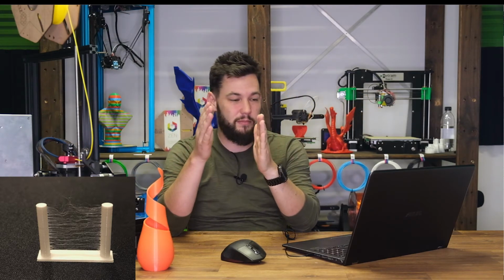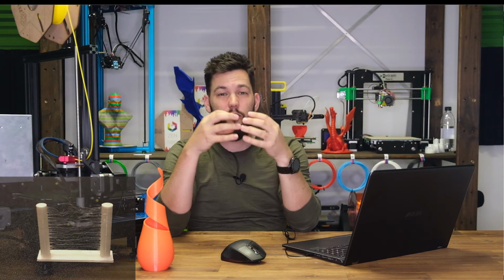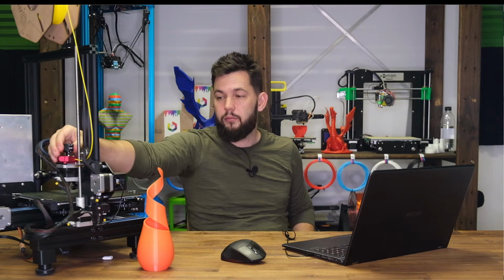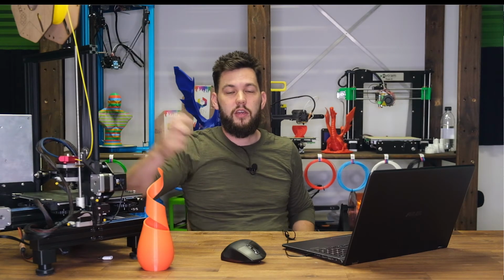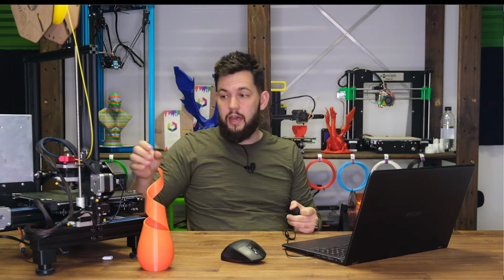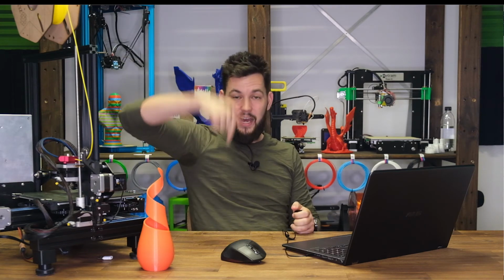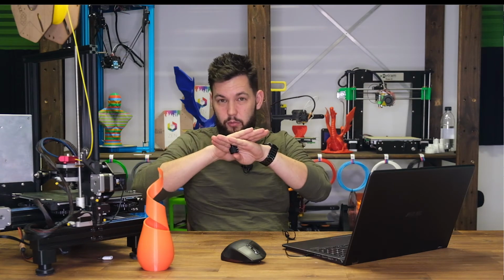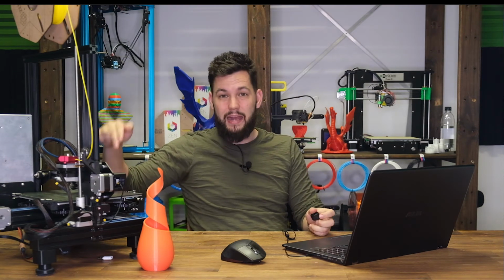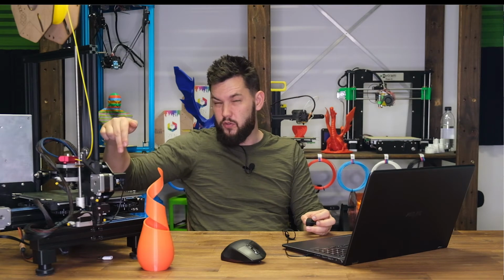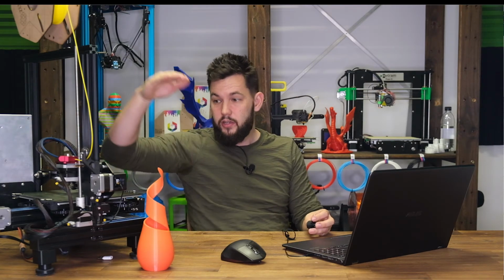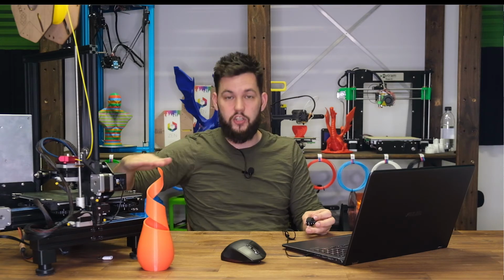So very similar concept. How we get around that is we do something that's known as retraction, and that is where the extruder motor over here, a little print on it, this will move backwards very quickly just before it starts to travel, which will suck the filament back up the nozzle, trying to make a bit of a vacuum and cut that filament, that excess filament off before it moves. As it gets to the location where it's supposed to be, the extruder will then extrude just enough to meet it back at the nozzle again and carry on extruding at the right point.